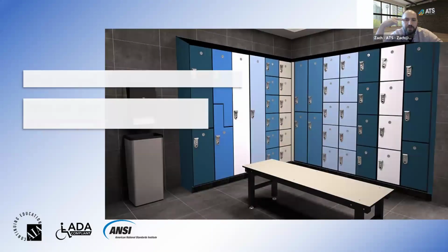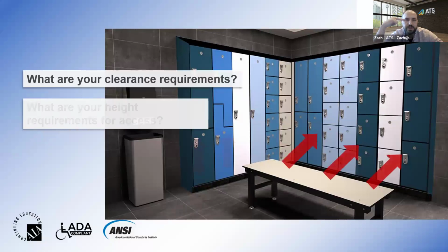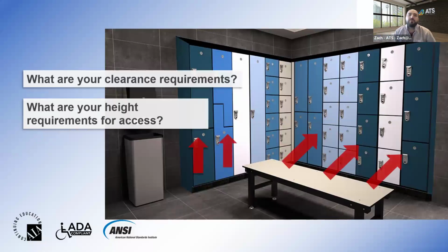And then some higher accessibility guidelines. Again, depending on municipality, you do see some of these percentages change. So for example, the Toronto Accessibility Design Guidelines, they require a minimum of 20% units be accessible to the nearest whole unit rounding up. So double check again your AHJ, any sort of local design guidelines that may go above and beyond